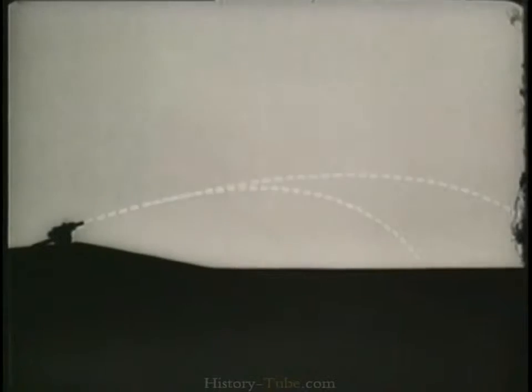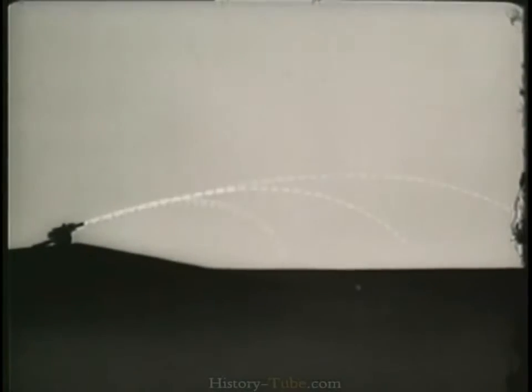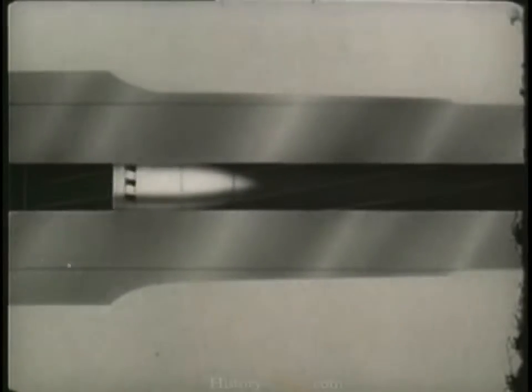To overcome air resistance and get greater range, we might streamline our cannonball, stretching it into a projectile. But look what happens. Our projectile tumbles, and the range is shorter than ever. We need something to stabilize our projectile in flight. One solution is to equip the projectile with fins. The use of fins solves the problem very effectively for mortars and some types of rockets, and the result is much greater range. Having the projectile spin is another solution to the tumbling problem.